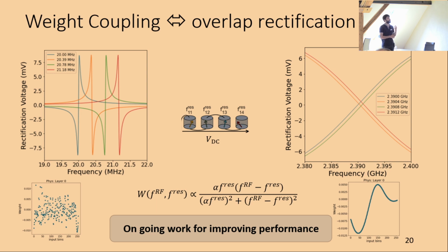And as you change the range of frequencies, this line width is increasing. What does it mean? It means that in the case we consider a chain and simply the first 4 resonators, you can see that the overlapping region amplitude might be not as important as in the case of the gigahertz range. Well, the range of rectification is quite wide compared to the case of the megahertz range.